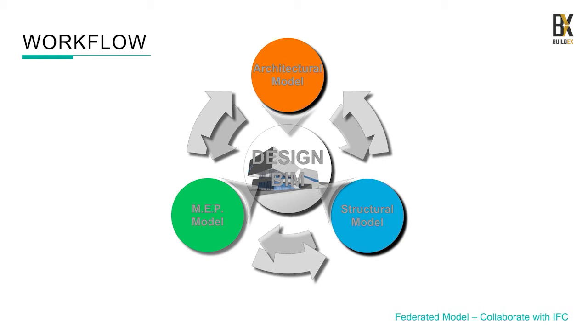Using an open format such as IFC, the collaboration process becomes easier. IFC stands for Industry Foundation Classes, a non-proprietary format developed by buildingSMART International. During the design, one of the benefits that a building information model provides is the ability to coordinate all disciplines in a 3D model, using other software to analyze the model and provide the contractors a fully coordinated set of documents, which in return saves money to the owner with potentially a lot fewer change orders and a more accurate bid.